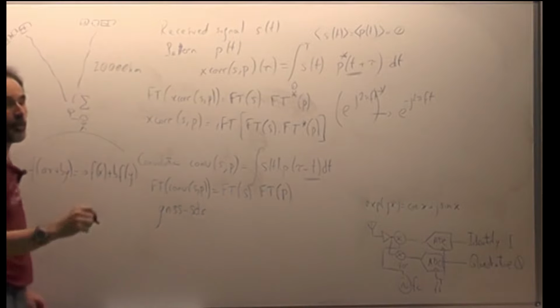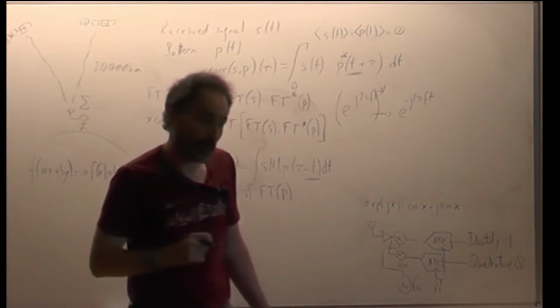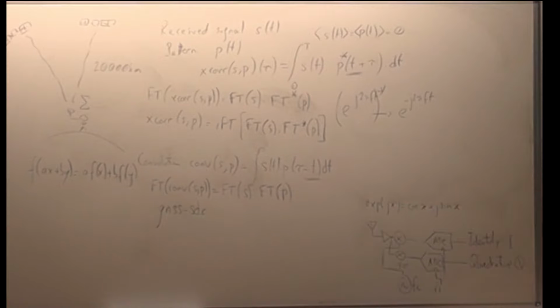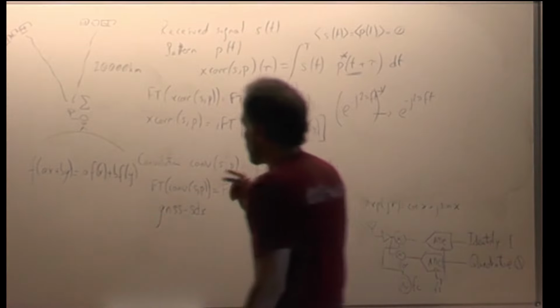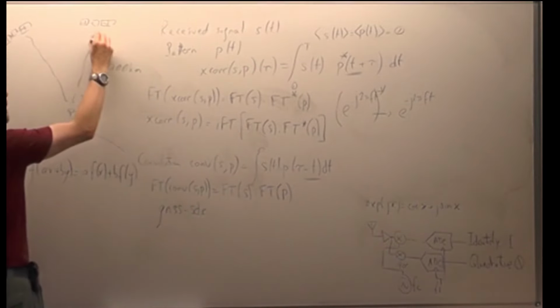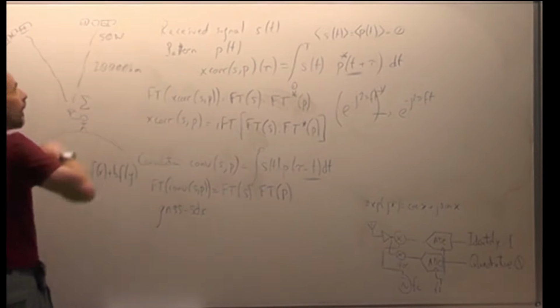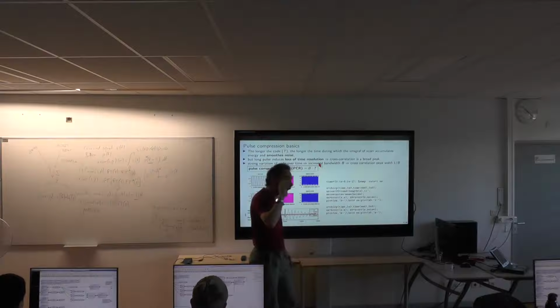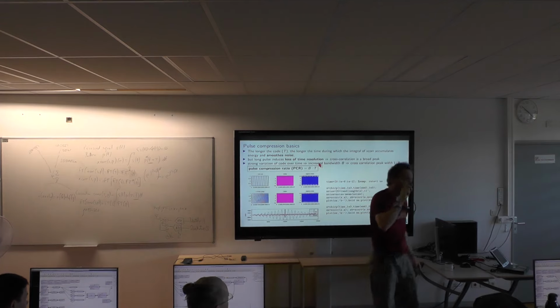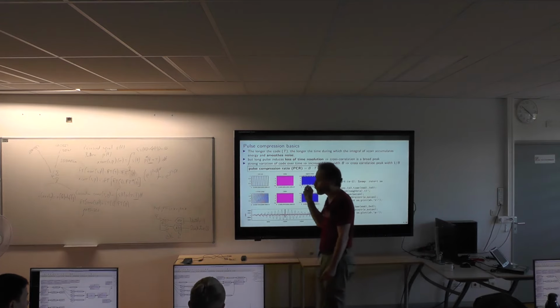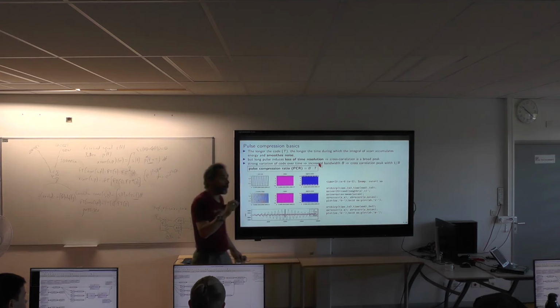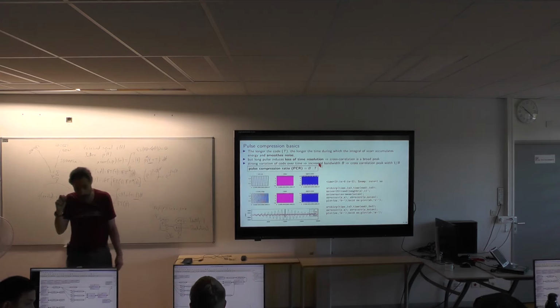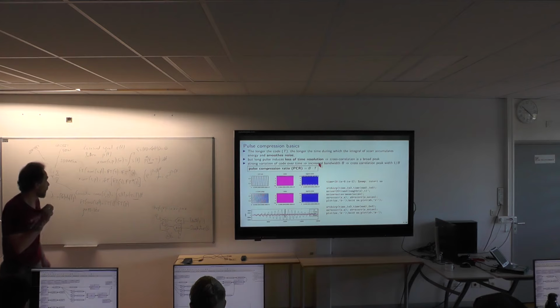Now I need to introduce one more concept, the concept that these satellites are located 20,000 kilometers away. These are medium Earth orbiting satellites. They are MEO satellites. And a GPS satellite is broadcasting 50 watt, 47 dBm. 50 watt is a light bulb. So you've got this light bulb 20,000 kilometers away, and yet through the power of signal processing, we can actually detect this information on the ground.